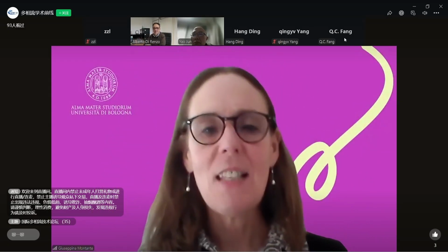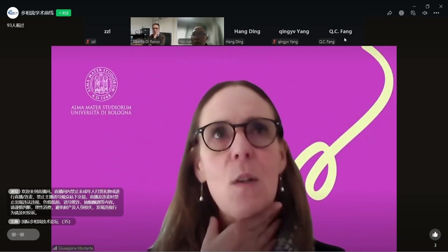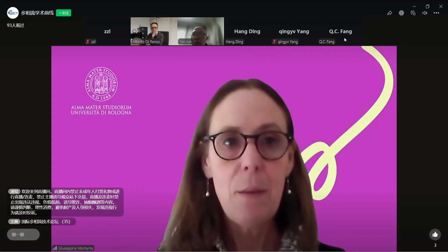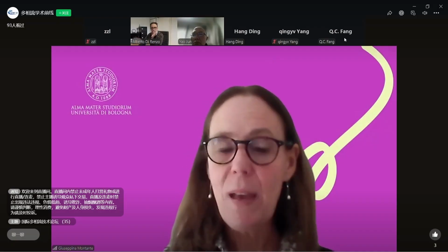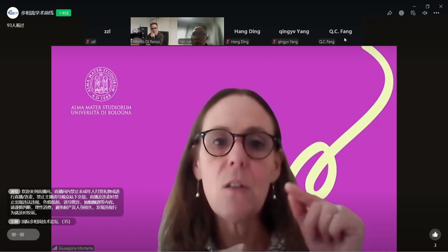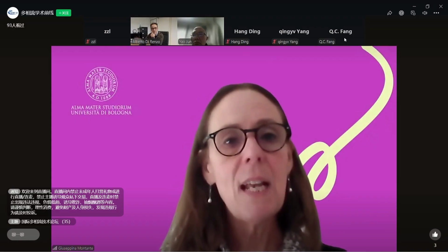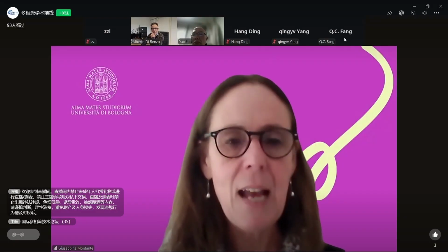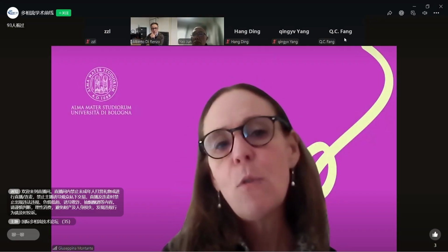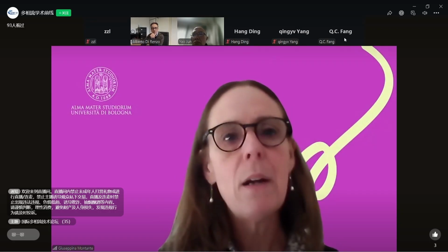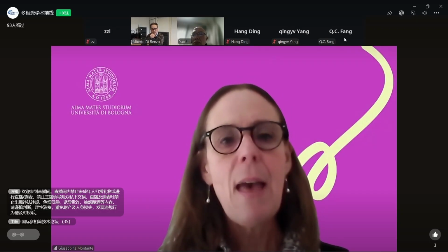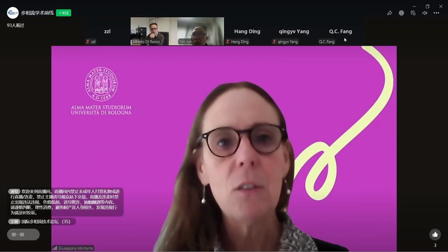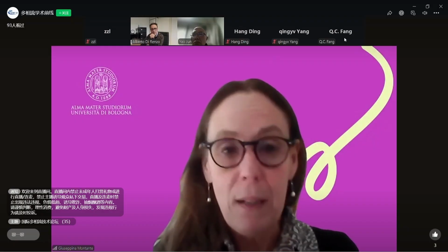Yes, indeed, I was too fast. Actually, I was referring to the case where the interaction between the particles prevails with respect to the interaction between the particles and the liquid. So in the realm of two-phase flow models in RANS, we have this granular flow model where we have a granular pressure, which is a modeling method that accounts for the particle-particle interaction.